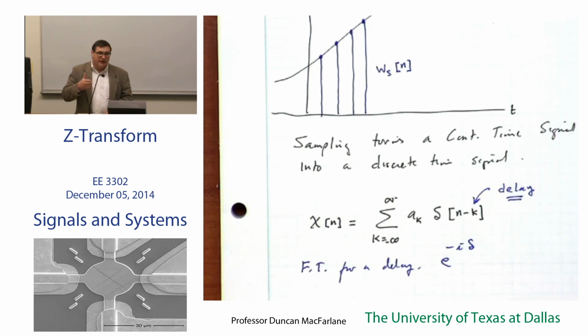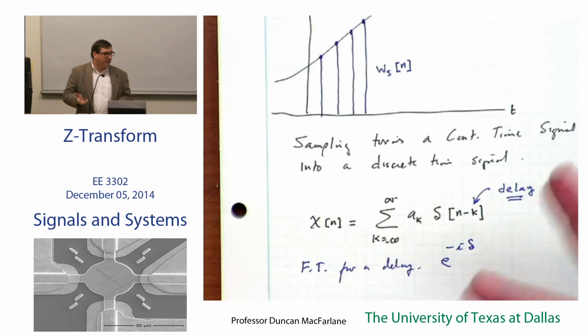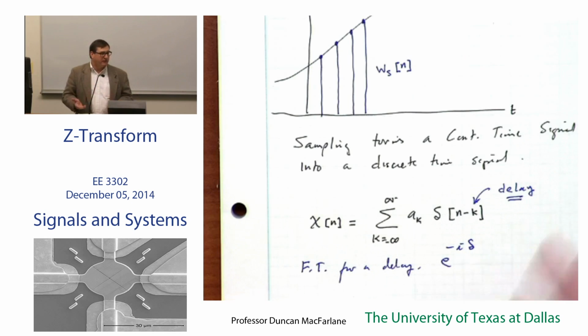But it's absolutely true that it's a phase shift as well. You can think a little bit about the differences between a time shift and a phase shift. At the most trivial level, they're exactly the same. But a phase shift is usually normalized with respect to frequency, so you talk in terms of how many radians of a phase shift versus how many milliseconds of a time shift. So units are a little bit different.